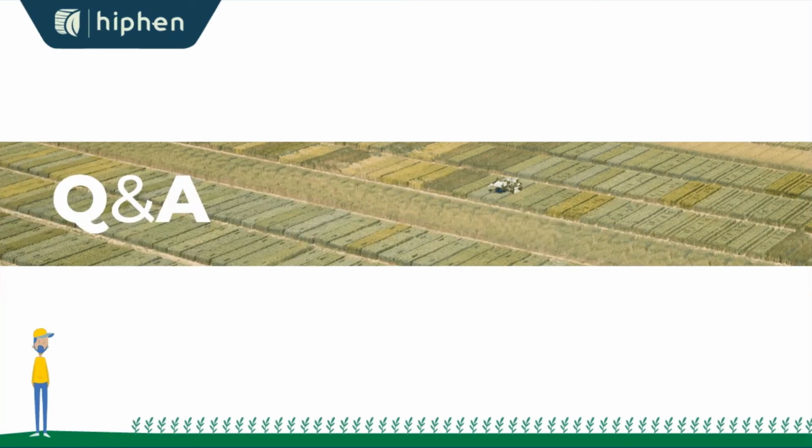Embedded in drones, the main question you need to ask yourself is, is it a global shutter, a mechanical shutter, a rolling shutter? So for example, there's a big debate lately, should you use a Mavic 2 Pro or a Phantom 4 Pro V2? So the Phantom 4 V2 has a wider opening angle, which is not good, but has a mechanical shutter, which gives you better images than the Mavic 2 Pro, which has a better lens with Hasselblad, but it's still a normal global shutter, and you have some resolution issues.